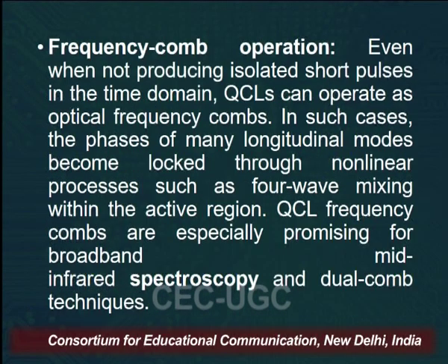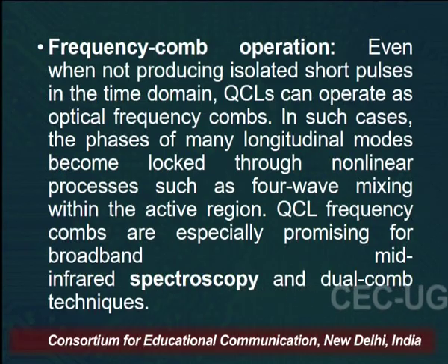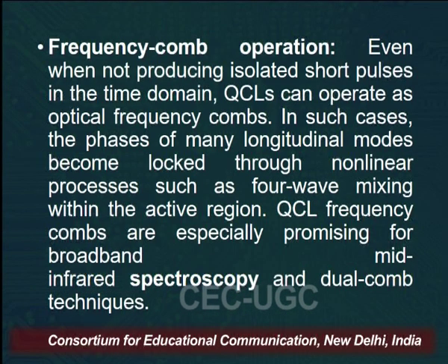Another is frequency comb operation. Even when not producing isolated short pulses in the time domain, the QCL can operate as an optical frequency comb. In such cases, the phases of many longitudinal modes become locked through non-linear processes such as four-wave mixing within the active region. QCL frequency combs are especially promising for broadband mid-infrared spectroscopy and dual comb technology.